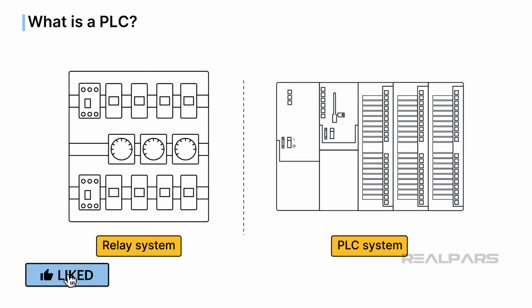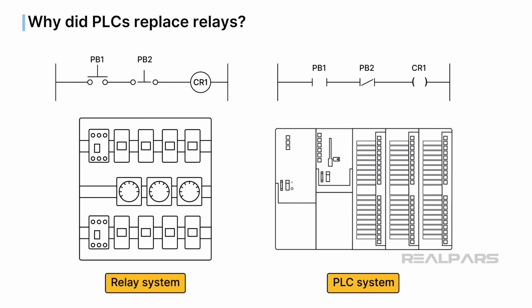The ability to program memory locations in a computer allowed a virtual digital representation of a physical relay. This enabled automobile manufacturers in the 60s to create assembly lines faster, with less labor. This efficiency led to PLCs being implemented over relay systems. Hardware-wise, the relay system that was used previously is now virtually inside the PLC. The decision-making relays are replaced by virtual relays and logic symbols.